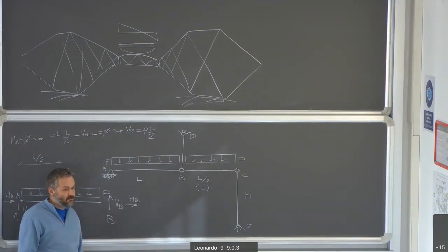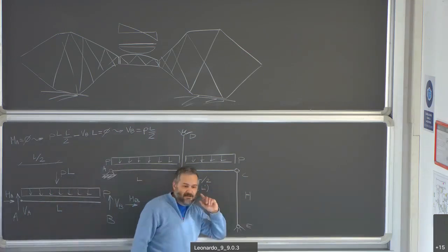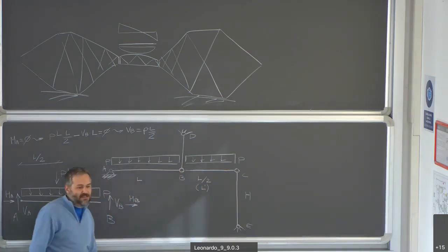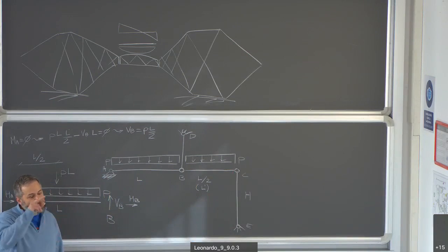If you stick to our usual assumptions, this is the most excellent example of an unstable structure, which is 3 hinges aligned. Generally speaking, a system consisting of 2 beams with 3 hinges is another statically determinate structure. But the most important condition is that the 3 hinges are not aligned. Otherwise, it's not stable. Okay?